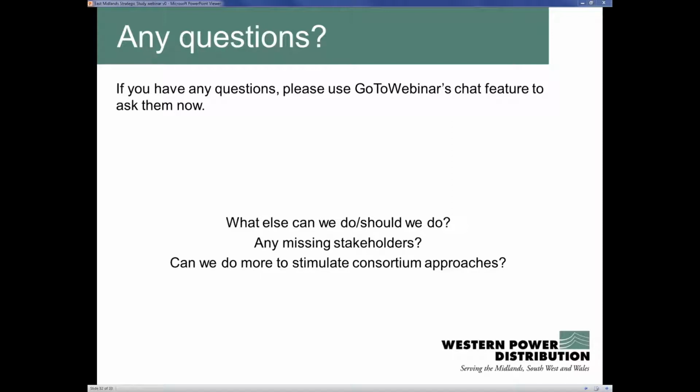That presents quite a significant problem for the distribution network operators, because when a system issue manifests itself on the network, it may not be exactly the same time as when we have lots of distribution capacity. So we could find that as a nation we need more generation, but there might be localized constraints on the distribution network that would forbid extra capacity being pushed out onto the network.